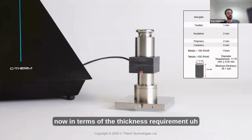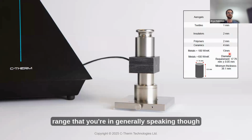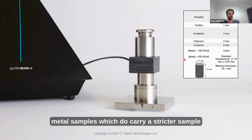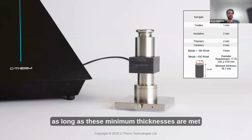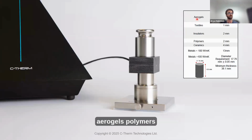Now, in terms of the thickness requirement, just very quickly going through here, you can see it ranges. It does vary depending on the type of material and the conductivity range that you're in. Generally speaking, with the exception of very conductive metal samples, which do carry a stricter sample size format, it is quite flexible. As long as these minimum thicknesses are met, there is no maximum size limitation. So again, everything from insulation, aerogels, polymers, ceramics, and of course metals.